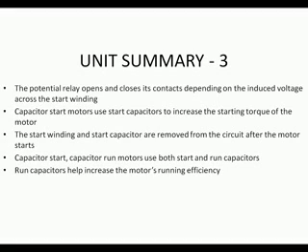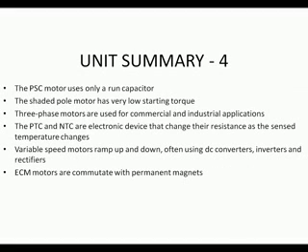Residences are supplied with single-phase power. Some motors are designed to operate at more than 1 voltage, and split-phase motors have a medium amount of starting torque and good running efficiency. The centrifugal switch opens and closes its contacts depending on the speed of the motor, and the current relay opens and closes its contact depending on the current flow through the run winding. The potential relay opens and closes its contact depending on the induced voltage across the start winding.